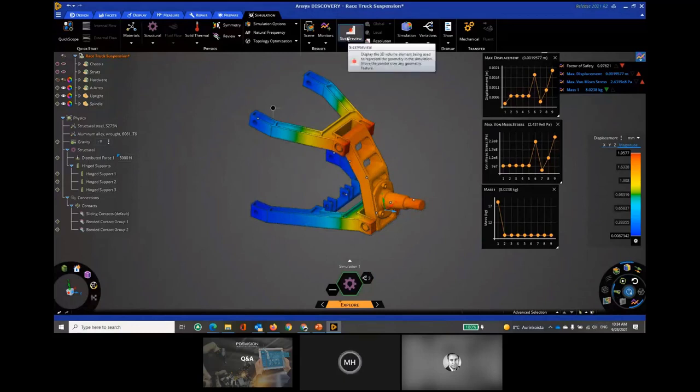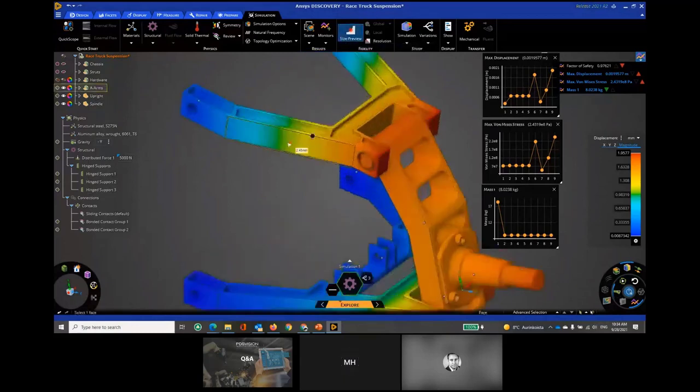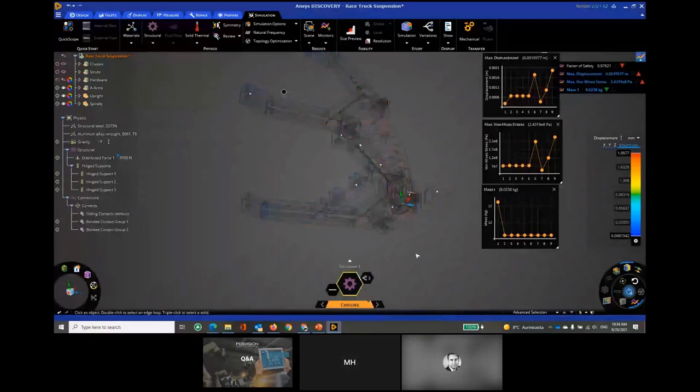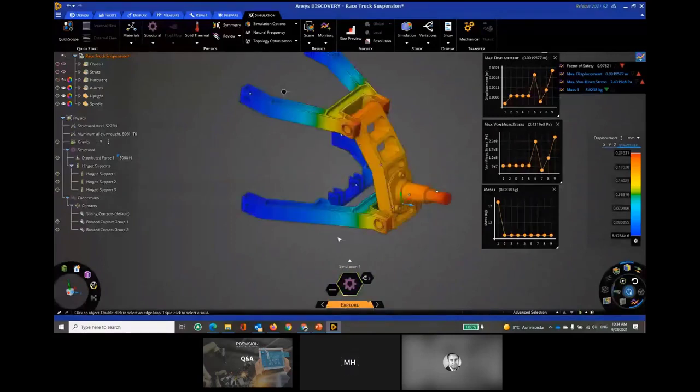First of all, we have this size per view, which gives you an idea about the size of the 3D element we are calculating the system with. It's around 2.45 millimeters. If I want to change this, you have this fidelity graph at the lower end of the screen. You can go in here and say, let's go for the maximum, and then you have a more intense final mesh. Computation takes a bit more time, and then you get the results, and my graphs are also populating.